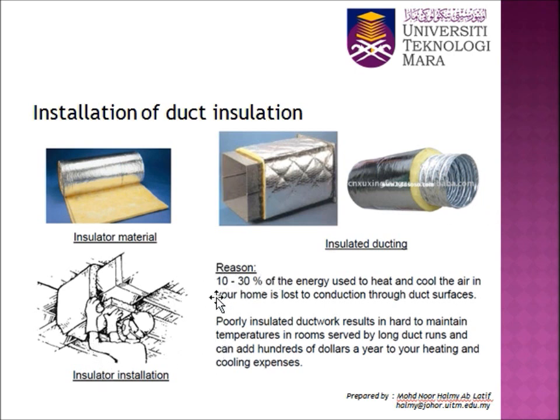So the reason why we need to insulate the ducting, 10 to 30% of energy used to heat and cool the air in your home is lost to conduction through duct surfaces. Okay. So poorly insulated ductwork result in hard to maintain temperature in rooms served by long duct runs and can add hundreds of dollars a year to your heating and cooling expenses. Okay.